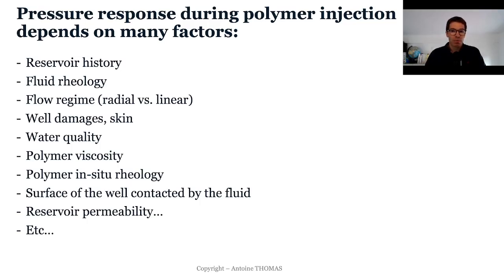We will, I would say, split into four categories, but if I had to put some keywords, it would be, of course, the reservoir, geology, heterogeneities. You will have the fill-up, the voidage replacement ratio. Then you will have the rheology of the fluid, the viscosity. You have, of course, the water quality, and anything that will be in this range. So the oil in water, the solids, the combination sometimes of solids and polymers, etc. So these are some of the important things that you need to understand and maybe be sure they are under control to avoid any unexpected problem.